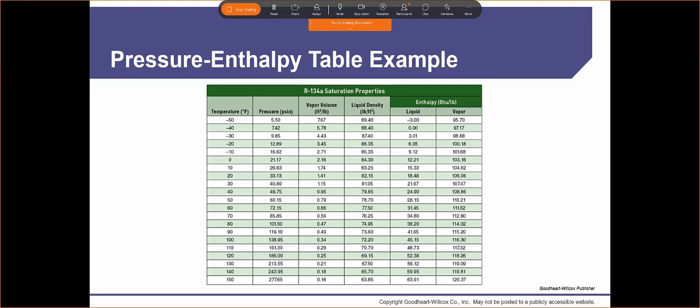All right, so we're going to have a larger line. We've got our vapor line in our system. They're usually either a 3/4 or 7/8 inch size. The reason being is because I have so much more room to fit all the vapor inside there to remove all the heat inside the house. All right, so we're going to let the vapor do all the work for us, and we'll just let the liquid reject the heat. Okay.